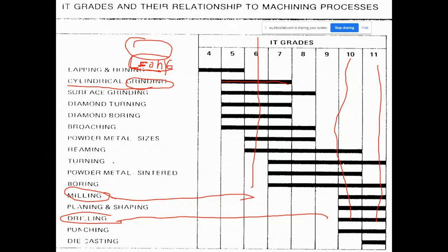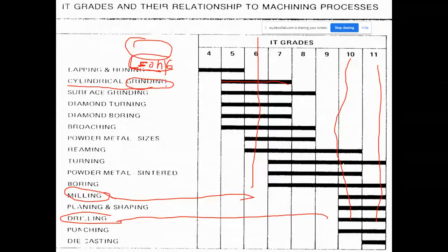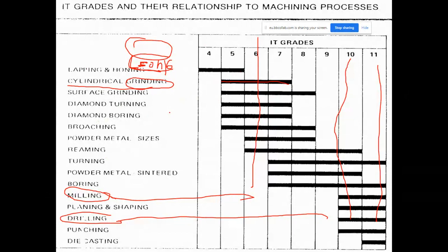Okay, then applying which process as the finishing, finalizing process can set the size of a feature, for instance, as 50H6, 50G7, 50R10, etc.? Referring to such a table, you can select the correct or proper finishing process.